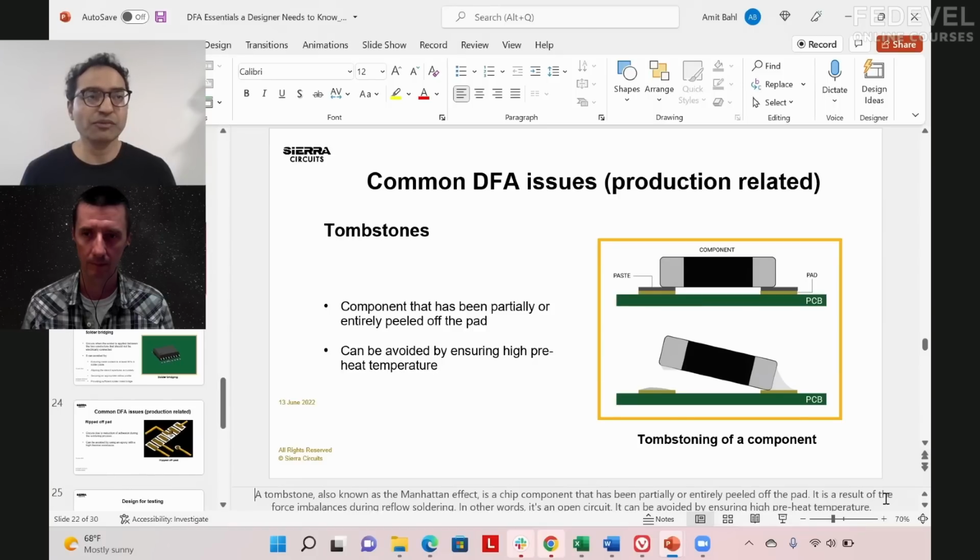And so when we have a universal issue like that, we do start checking for that. So via in pad, via close to pad, those are design rules that we will analyze designs for, so that the customer can make the change. And if they can't make the change, then we'll do the best we can for that product, for that build. But at least they'll learn for next time not to do that same thing, because it could cause a potential problem.